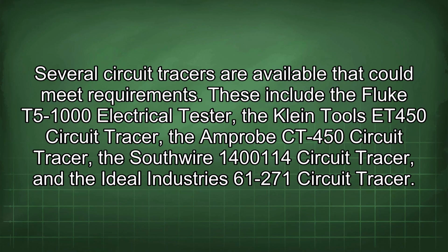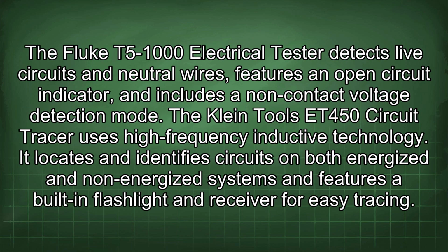Several circuit tracers are available that could meet requirements. These include the Fluke T5-1000 electrical tester, the Klein Tools ET450 circuit tracer, the Amprobe CT-450 circuit tracer, the Southwire 1400114 circuit tracer, and the Ideal Industries 61-271 circuit tracer. The Fluke T5-1000 electrical tester detects live circuits and neutral wires, features an open circuit indicator, and includes a non-contact voltage detection mode.